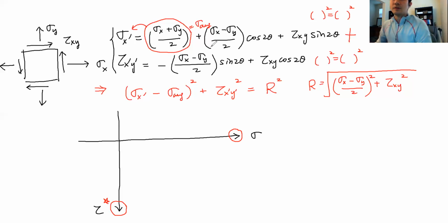Anyway, I'm going to repeat and review the development of the Mohr circle. To develop the Mohr circle, we have to start with three points, C, A, and G, and these are the same letters as the points in the textbook. The first point is going to be the center, and the coordinate of the center is going to be sigma average, and the vertical component is going to be 0.